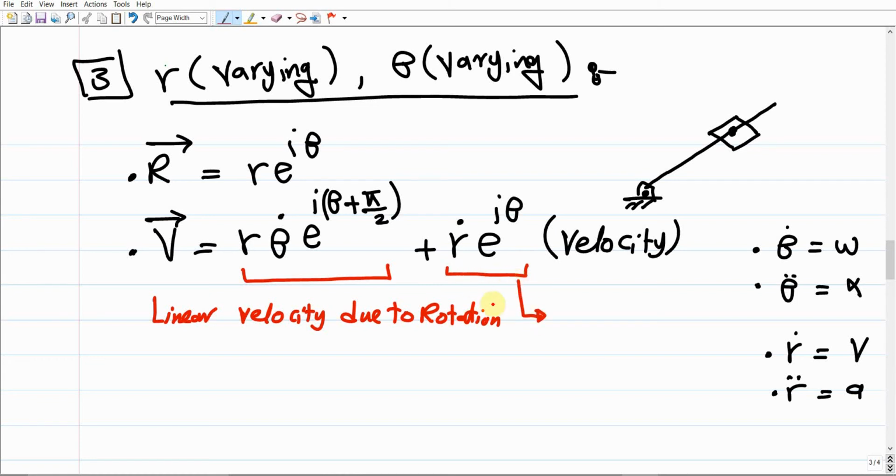It means this is a sliding velocity, a linear velocity, with no angular velocity. It is the sliding velocity of the slider itself. This explains the slider, because if you give rotation to this link, the slider intuitively is going to be shifted, sliding over the link. That's why we say r is variable, right?